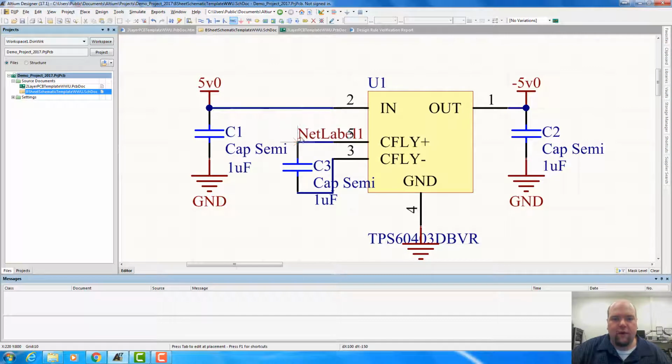When anything we're dropping is in a location where it's going to make electrical contact with another signal, the little crosshairs turn red. So we have sort of faint black crosshairs, and we have bold, longer red crosshairs now. It's pretty easy if you have a snap grid to see when that happens anyway, but it's always good to tell. You can know you're actually connecting to a signal if you see those red crosshairs. So we're going to drop that label.